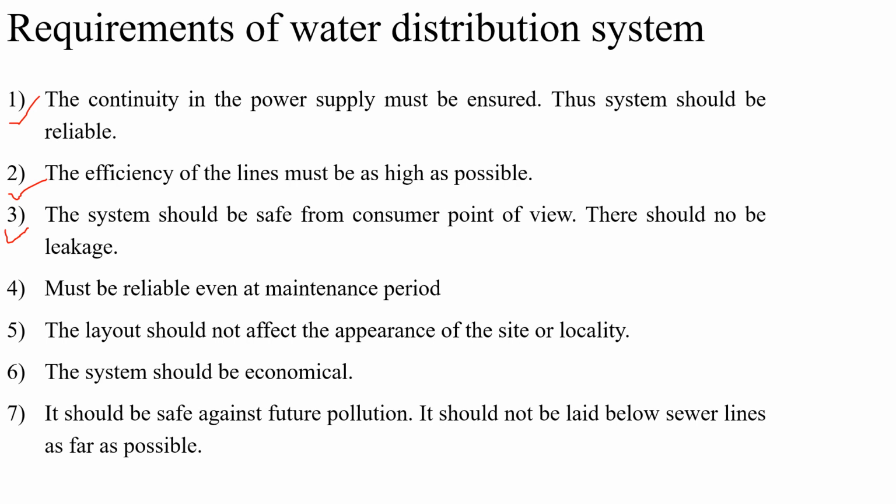The layout should not affect the appearance of the site or locality. It should not spoil the beauty, right? This should be economical. The cost should not be so high that the distribution system becomes costlier, right? And it should be safe against future pollution, right? It should not be laid over sewer lines as far as possible.